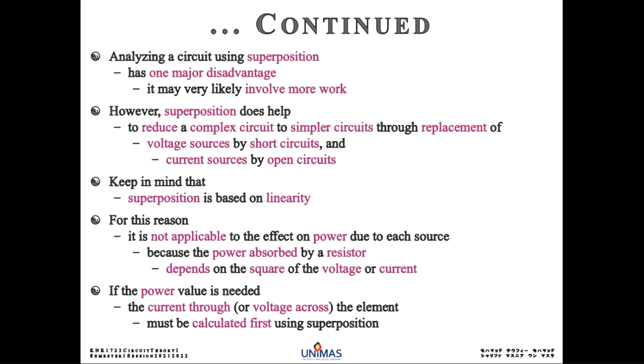Right? So this is all theoretical. Analyzing a circuit using superposition, one major disadvantage, it may very likely involve many more works. Of course, you solve one by one. However, superposition does help to reduce a complex circuit to a simple circuit, by replacement of voltage source by short circuit and current source by open circuit.